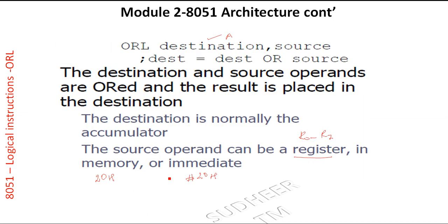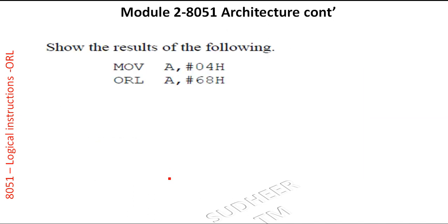So let us see what will happen after executing an OR operation. So what is OR operation? Suppose we have two inputs, say A and B, and we have the output. So possibilities are 00, 01, 10, then 11. Basic logical operation: 0 plus 0 is 0, logical operation is plus, 0 plus 1 is 1, 1 plus 0 is 1, 1 plus 1 is 1. So output will be 0 only when both inputs are 0. If at least one input is 1, output will be 1.